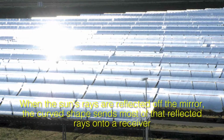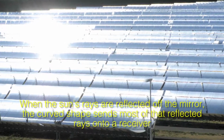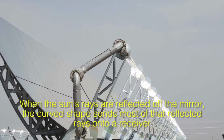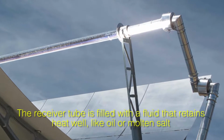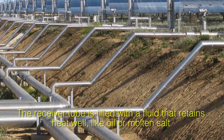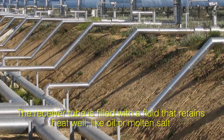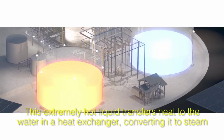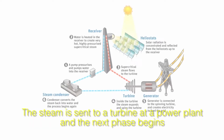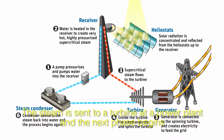When the sun's rays are reflected off the mirror, the curved shape sends most of the reflected rays onto a receiver. The receiver tube is filled with a fluid that retains heat well, like oil or molten salt. This extremely hot liquid transfers heat to the water in a heat exchanger, converting it to steam. The steam is sent to a turbine at a power plant, and the next phase begins.